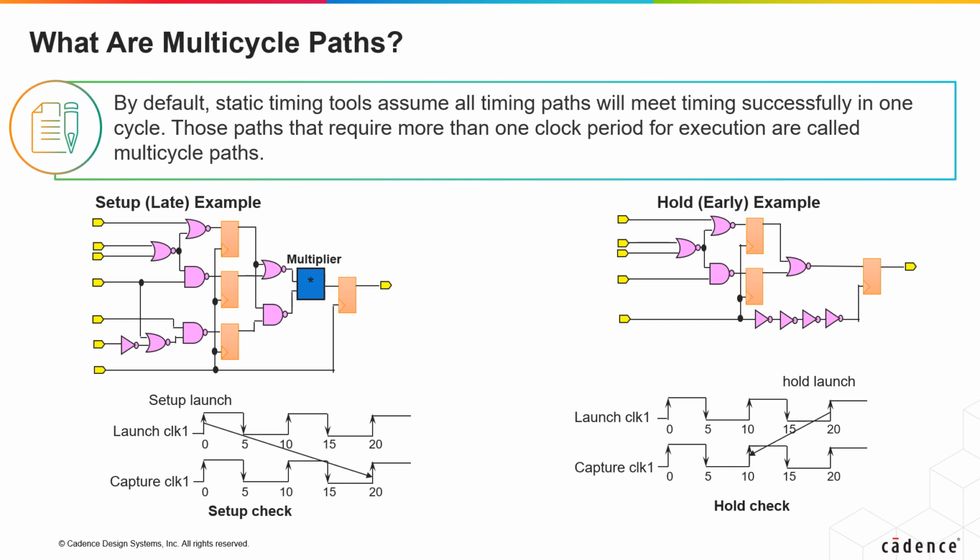Some multipliers are pipelined to one cycle, but when the output of the multiplier does not require pipelining, it must be considered a long path and a multi-cycle path must be defined through the path. The rest of the design must be considerate of this known long path and use its output only after certain cycles. Then it becomes a known multi-cycle path.